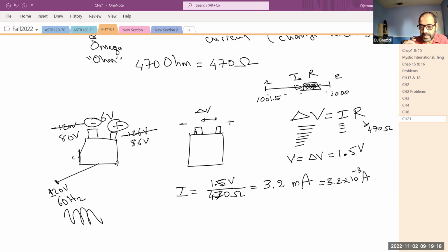So all we care about for that battery, when you put the multimeter, you took one end of the multimeter device here, and the other end in here, and you turned the dial, the knob, toward where it says I want to measure volt, and I want the tolerance to be up to 12 volt, because there was a setting for 3 and 12 and so on. If I set it at 3, it's going to be off the chart. The needle will go all the way to the end because it knows it's more than 3 volts. But if you know that the answer is less than 12 volts, you set it to 12 volts and the needle went to the middle. It was reading exactly 6 volts.